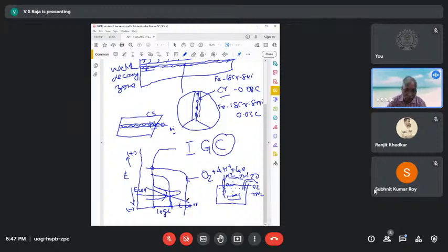That means I need a larger amount of oxygen in order to passivate again. How much oxygen content is required is a different story that one has to study. But it will undergo active dissolution unless there's a sufficient amount of oxygen present to repassivate again.